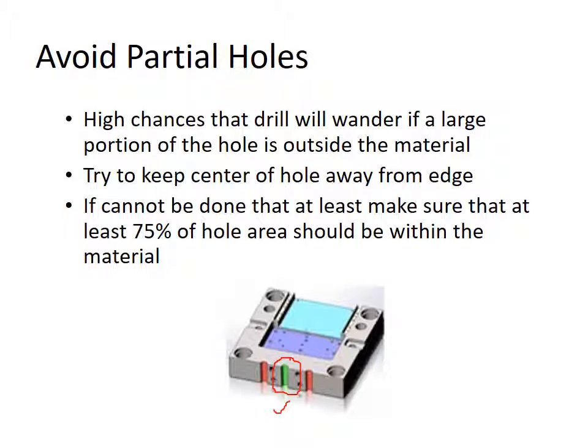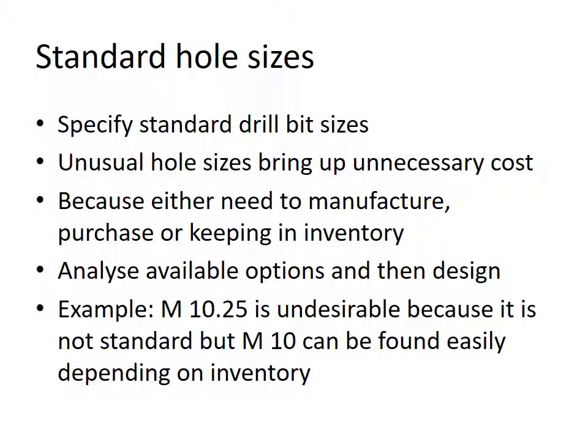Partial holes should also be avoided, and try to keep the center of holes away from the edges as much as possible, because otherwise uneven forces on the drill bit would result in vibration, an imperfect hole or even breakage of the tool, and may ruin the workpiece. So it is advised to keep at least 75% of the hole area inside the material to prevent such damages, which may increase cost due to scrap. Hence the green one should be preferred over the red one in the shown design.